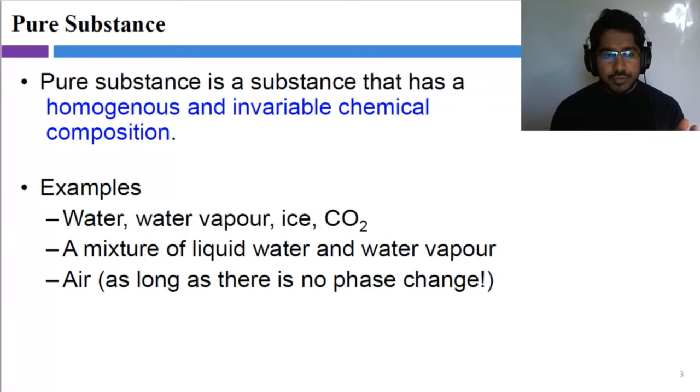if we try to fit this into our definition, then you can see in a water, liquid, and vapor mixture, when we go across the mixture, we don't have a chemical variation, like chemical composition of the mixture does not change. The proportions, they stay the same. So that is one important notion. So whether a substance being pure or not does not depend on the phase of a substance. It can have a phase mixture, or it can have liquid, solid, or vapor.